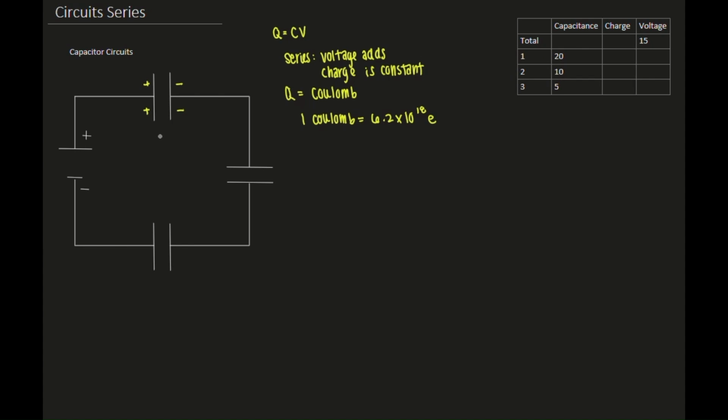We're going to label this capacitor 1, capacitor 2, and capacitor 3. And this will be our total voltage of the system connected to some power source. The capacitor is opposite of what the resistors were. If you remember back in our video before, the resistors, when they're in series, is simply the sum. They just add across the circuit. For capacitors, when they're in series, it's the inverse of the sum of the inverses. You can call it total capacitance, or the other term is equivalent capacitance. You can say the same thing for resistors, total resistance, or the equivalent resistance, which is essentially the overall resistance or capacitance of the circuit we're specifically dealing with.